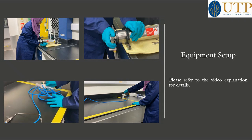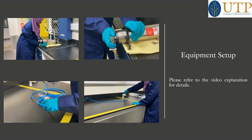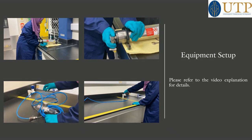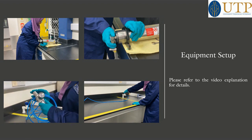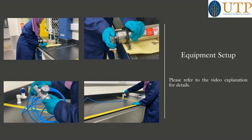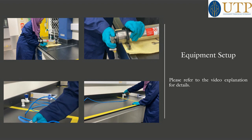This is an air flow regulator, and we will connect this system with my accumulator using this one, and this one I will connect with an air supplier. Okay, so now it's already connected. When my work is done, make it like this. When you want to increase the pressure, just move it like this. For our flushing, we need only 35 psi. So let's see how to do it.